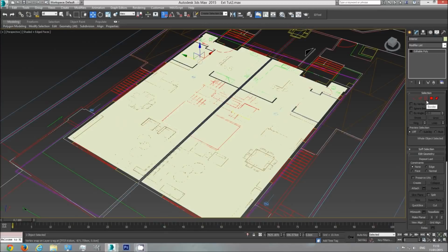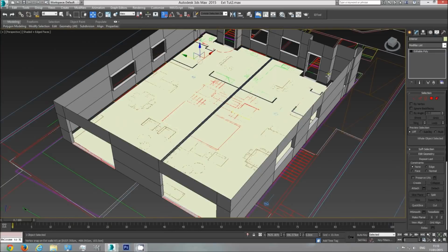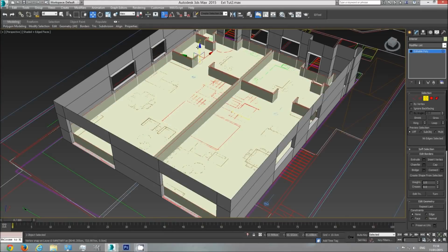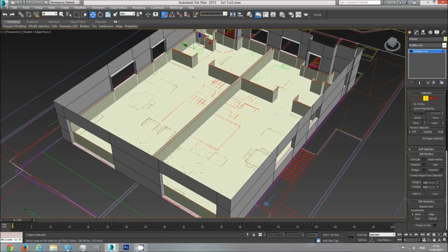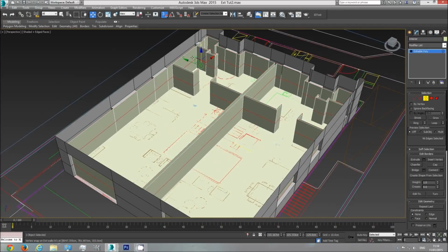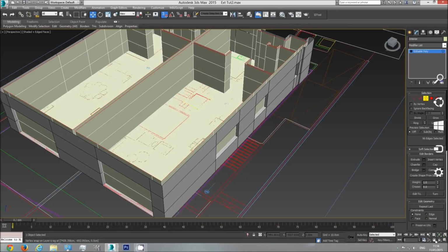Now, same thing as I did with the exterior walls. By the way, let's right click, unhide all, and just bring them back. I'm going to select the interior, and I'm going to select all the border of the interior and just take them up, shift drag on up axis to this point, the bottom point of the window, and shift drag up to this point, the top point of the window, and shift drag up to the ceiling level. So that is fine.